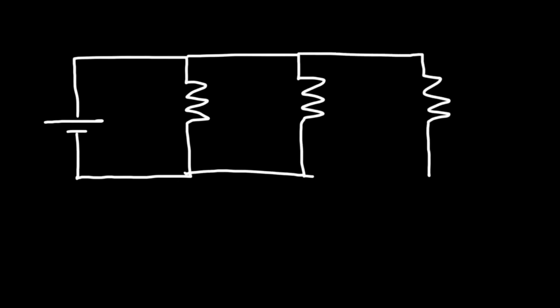In a series circuit, the current flowing through the resistors that are connected in series is the same, because the current only has one path in which it could flow. In a parallel circuit, the current has multiple paths, and so it could vary. However, notice that whenever resistors are connected in parallel, the voltage across those resistors is the same.